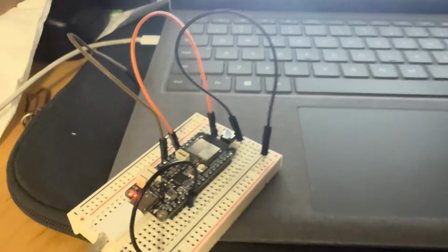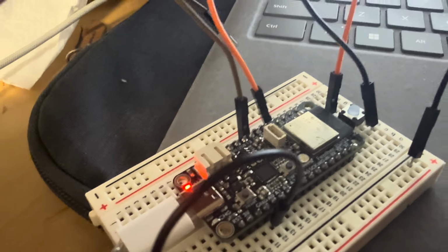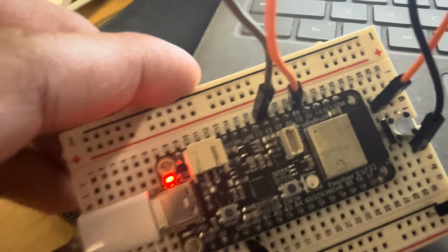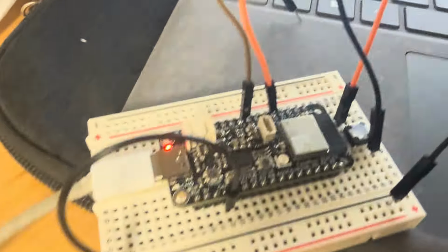So yeah, that's pretty much it, at least for the setup. Again, for the pins, it's just pretty simple. The only thing that really matters was GPIO 32 for the push button, and then the GND pin, and then also for the touch pin, it would just be GPIO 12. And that's it.